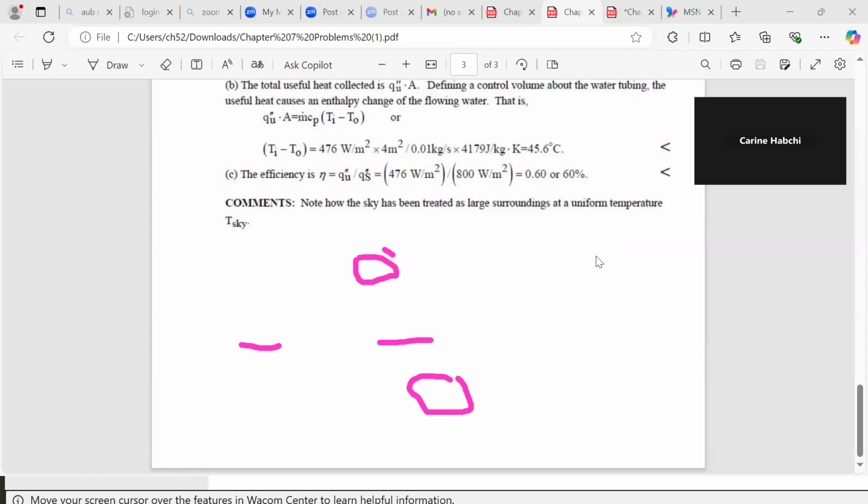You first optimize the orientation of your system to increase the incident angle, because as your friend said, if you don't have a good inclination, you have to project to get the perpendicular component, and you need to multiply by the cosine of the angle. So you need to orient your solar collector in a way that maximizes the absorption. You also need to insulate the backward side of your heat exchanger so as not to have losses to the external environment. So you have a lot of possibilities of losses. If you tackle them, you can increase the efficiency of your system.